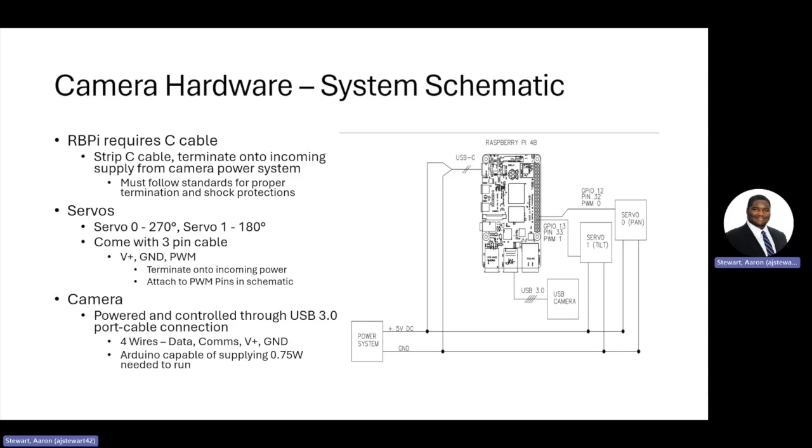And the Raspberry Pi will actually specify 15 watts of power. So that'll be about, at 5 volts, roughly 3 amps. So that should be more than enough for the Raspberry Pi to operate. It won't actually use all that current, but that's just for worst case scenarios.